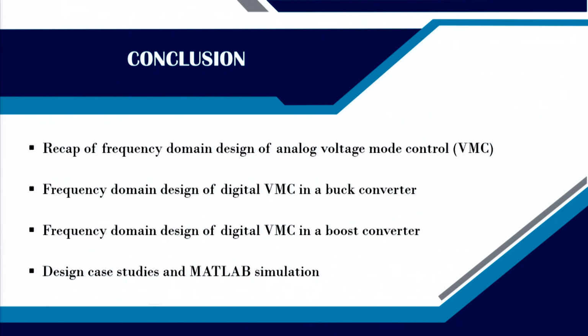By this frequency domain approach, we can still maintain the same continuous time approach and add the delay. But in the subsequent lecture, I will be showing this continuous time model is nice when you talk about small signal based design, but as we want to push for large signal based design, then this model cannot predict different types of instability, such as subharmonic instability. Then we need to go for the actual discrete time model, and that we will be taking in the subsequent lecture.